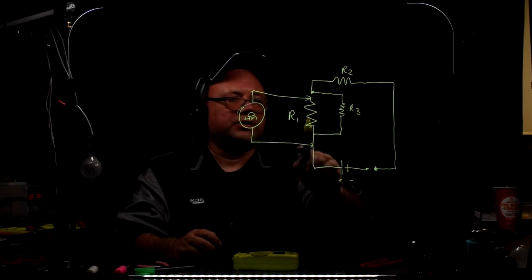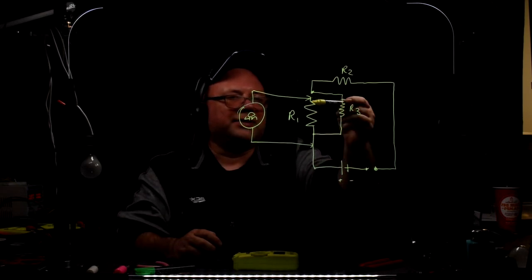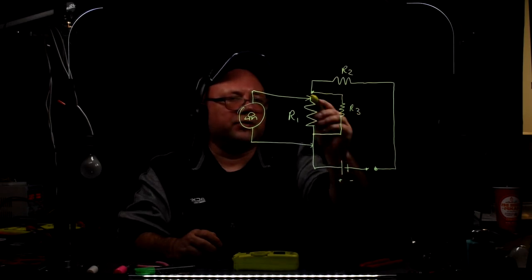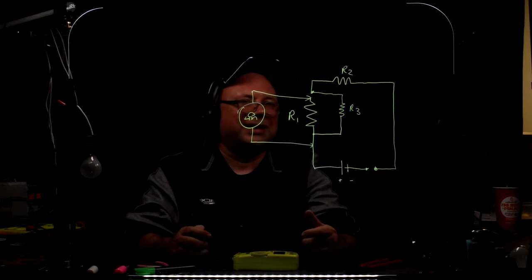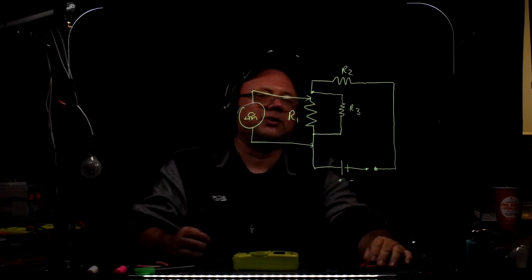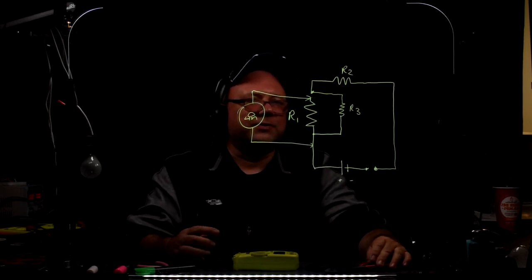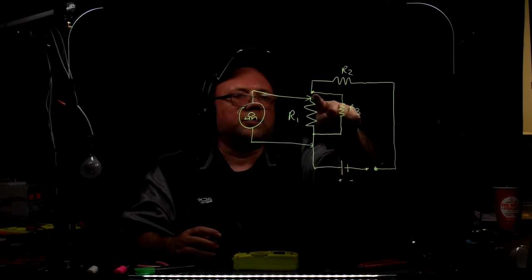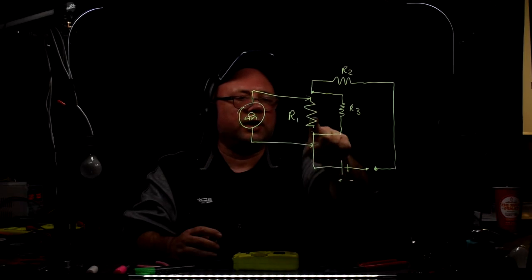Now this resistor is still connected on this side here. However, it doesn't have a closed path with anything else. So that's considered something that you can say lifting one leg. Someone's going to say, if you want to measure a resistance across some component, all you have to do is lift one leg, which means we broke one. We could just do, sure, you could do both of those, but then you have to connect that to here.